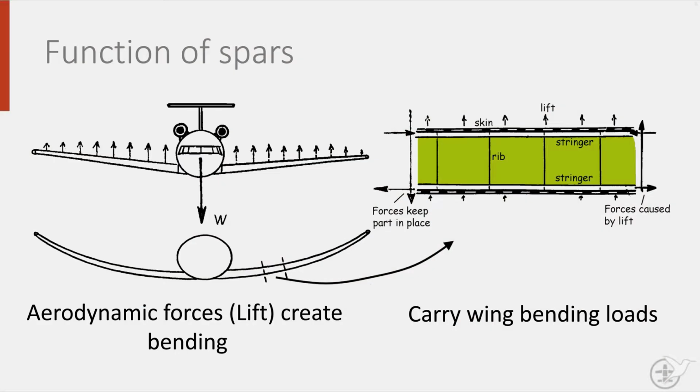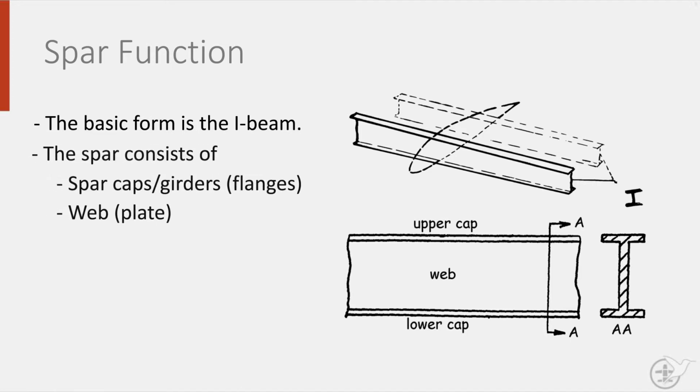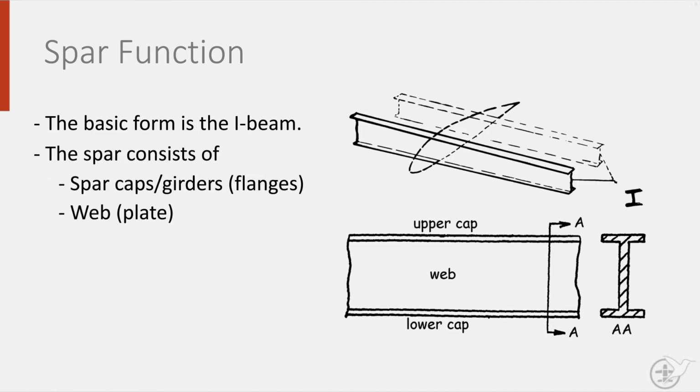When talking about aircraft wings, we must also discuss spars. They are the long spanwise beams in a wing. Spars have as a main function to carry the bending loads in the wing generated as a result of the aerodynamic forces on the wing. A spar has an eye-shaped cross-section of some sort with a web perpendicular to the wing skin and flanges parallel and attached to the skin.